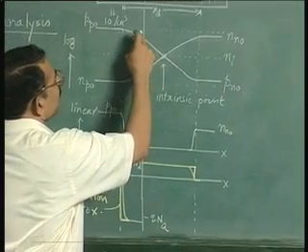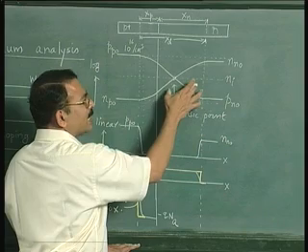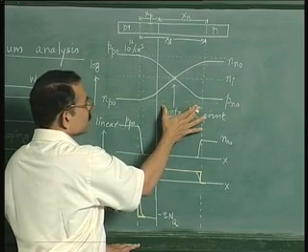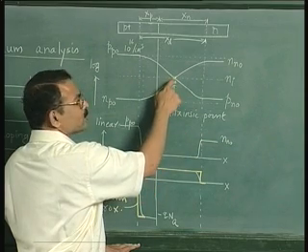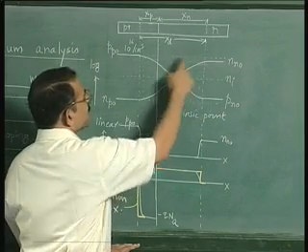Okay, so most of the variation in the carrier concentration is occurring on the n side, that is the lightly doped side, where the width of the depletion region is more, and that is why in fact the intrinsic point lies on the lightly doped side. Okay, this point is on the lightly doped side because most of the variation is taking place here.